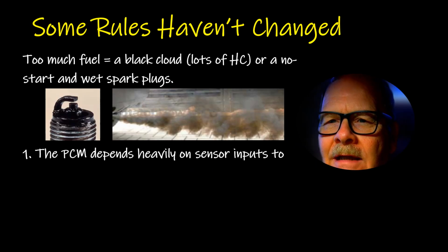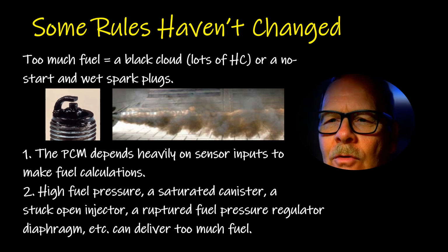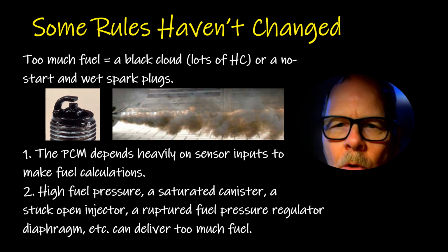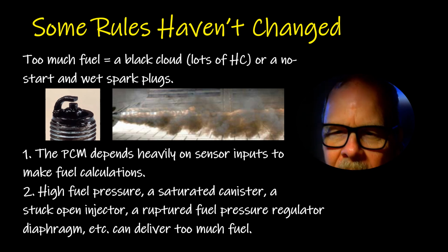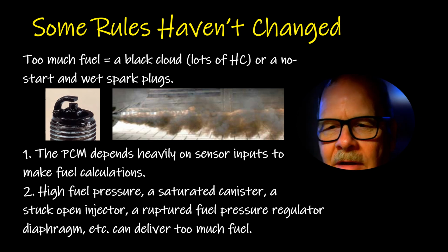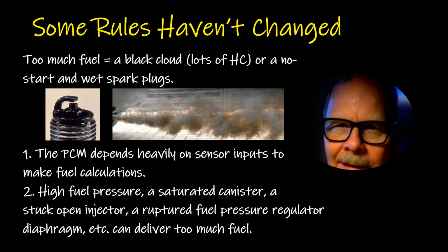Now, some rules haven't changed. Again, that's the same title I had on the other. Too much fuel makes a black cloud and lots of hydrocarbons, or a no start and wet spark plugs. The PCM depends heavily on sensor input to make fuel calculations. Of course, it needs good airflow too, and if the air filter is completely clogged up, you're going to have issues.